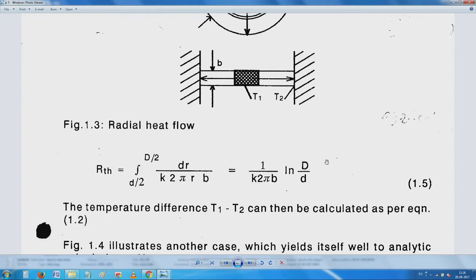This follows that Pentium cooler which I have shown you. If you see that radial modeling there, the base of it, as in the first picture I showed you, is a circular heat sink, and at the base of it the square pad is mounted, and from there radially we have the fins. At those points, when you are calculating how the heat reaches the end point, you will be able to use these expressions easily, and this is already built into most of the CFD or FEA packages.